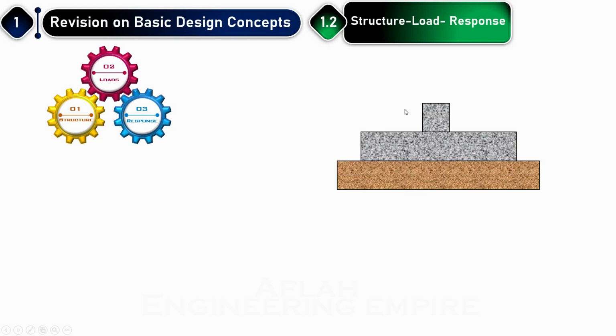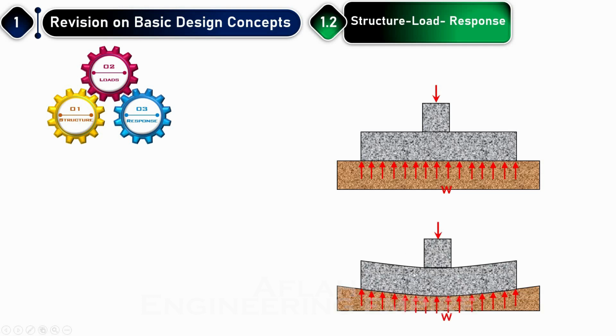Now, for example, again, if we take this isolated footing, due to the load, there will surely be a pressure in the soil. Due to this load, the element is expected to deform in such a way, because the soil is not, as we assume in some of the software analysis, a fixed support, but a kind of elastic member at the bottom. The soil will deform like this. So due to this, we are expecting that the bottom part will suffer certain cracks. So that's why most of the time you see reinforcement in the isolated footing around the bottom and opening upward like this.